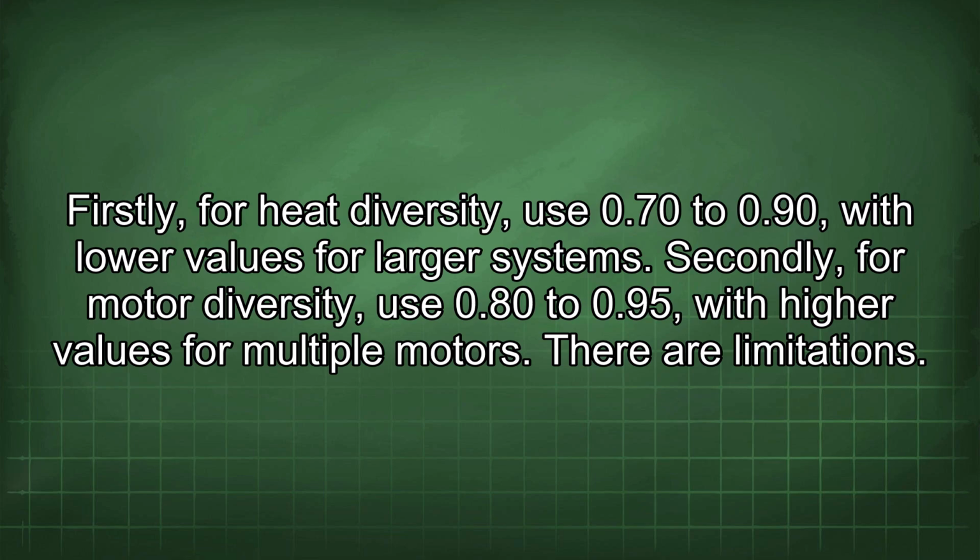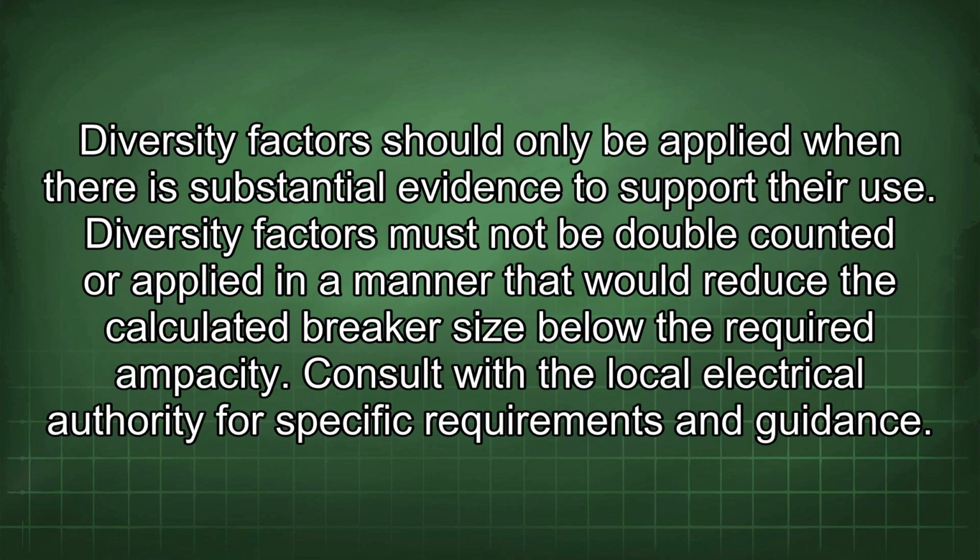There are limitations. Diversity factors should only be applied when there is substantial evidence to support their use. Diversity factors must not be double-counted or applied in a manner that would reduce the calculated breaker size below the required ampacity. Consult with the local electrical authority for specific requirements and guidance.